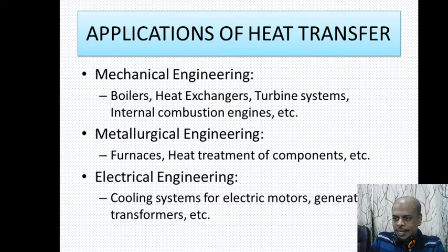It is suddenly expanded on a turbine, which is a steam turbine. So on that steam turbine, because of the sudden change in pressure, that pressure energy is converted into mechanical energy by rotation of the turbine. Then the sudden fall of pressure also causes a sudden fall of temperature, and there is heat exchange, and it becomes the application of heat transfer.